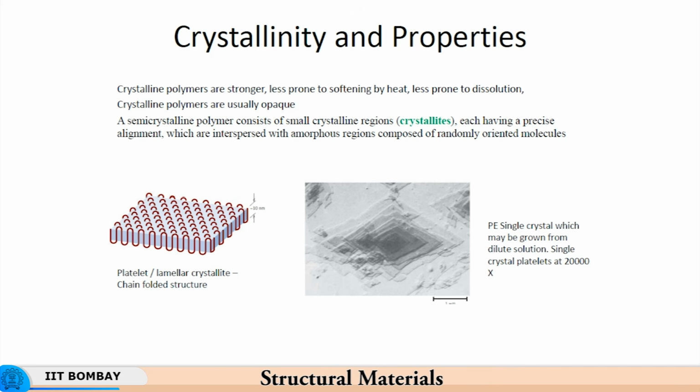So basically where you need much greater structural strength, you would prefer a crystalline setting. In the same product, part is crystalline and part is amorphous. As a result, part of the product is transparent, and part is opaque but mechanically and structurally stronger than the transparent regions. So this is how you can tailor the properties you want, depending on the crystallinity obtained in different regions.